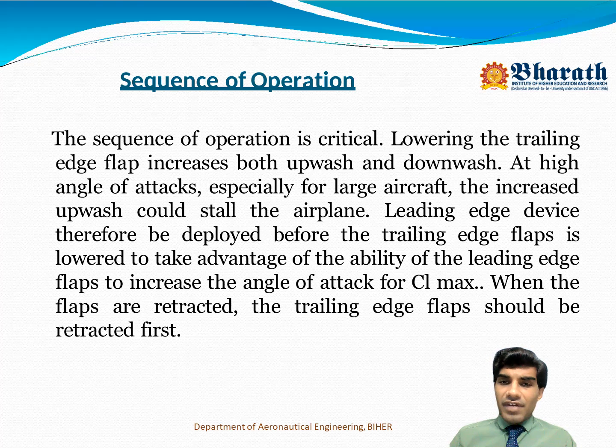Lowering the trailing edge flap increases both upwash and downwash. If you lower, meaning open, the flaps, it will increase both upwash and downwash. At high angle of attack, especially for large aircraft, the increased upwash could stall the airplane. So this is one problem. If a stall condition happens, and the pilot is not able to control it, then a crash can also happen.